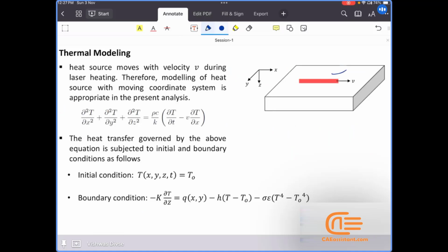So just surface heat flux, as I see here. But due to heat transfer phenomenon, heat may transfer in the width direction or in the depth direction. Convection is possible, radiation is possible, and this is a very high temperature laser beam. Ambient temperature is always available, so convection is also possible. So all three modes of heat transfer will be active as your moving heat source is there.